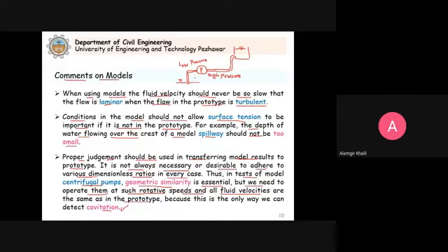When the pressure becomes so low on the suction side, it is minimum before the water enters and moves over the blades of this pump runner, which we also call vanes or blades. Cavities will form, because when the water boils, bubbles will form. When these bubbles pass over the runner blades, they move from low pressure to high pressure.